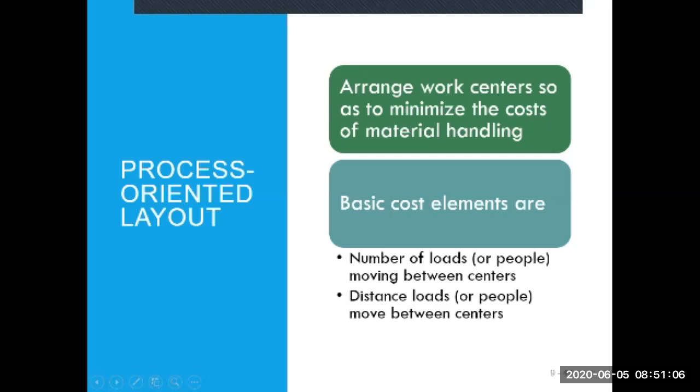So when you arrange the work centers, the objective is to minimize the cost, so you have to consider these two things: the number of loads moving between centers and the distance loads move between centers. Only these are most important.